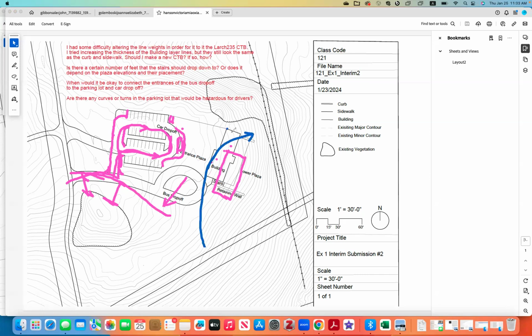If my building is still here, my swale needs to go like this, or it needs to go into the vegetation. If it's this situation that you don't have enough space, okay, we also want to leave enough space for it. If I want to direct my water to the vegetation here, I need to design a depression over here.